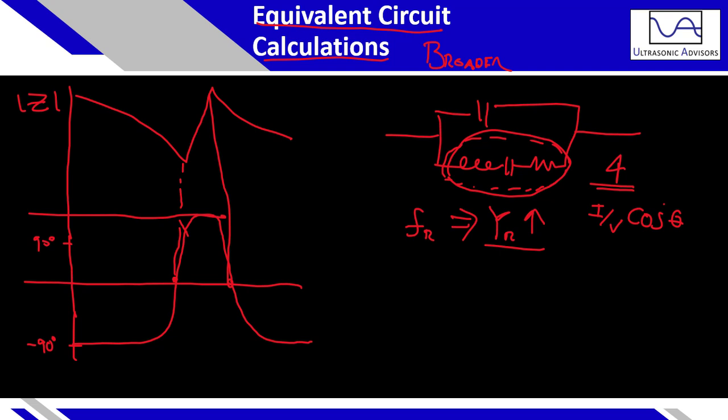So basically the frequency of maximum power dissipation is the frequency at which the real admittance is the highest, the real component being the dissipation of power. You could also, at that same time, if you wanted to do it in a different way, get your voltage times your current amplitude.